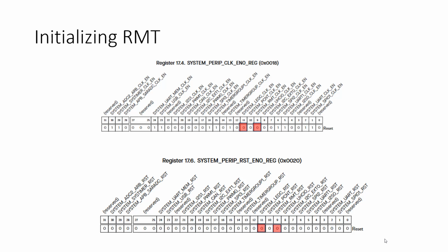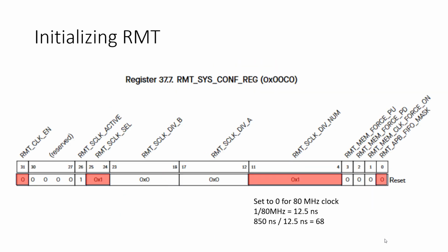Okay, but in the lab sheet, I just give you the absolute address for these two. I have a table in there. If you forget to turn on the peripheral like this before you try and write to some of the peripheral registers, your writes will not stick. So make sure you do this, or else you'll be wondering why your writes aren't taking effect. So very important.